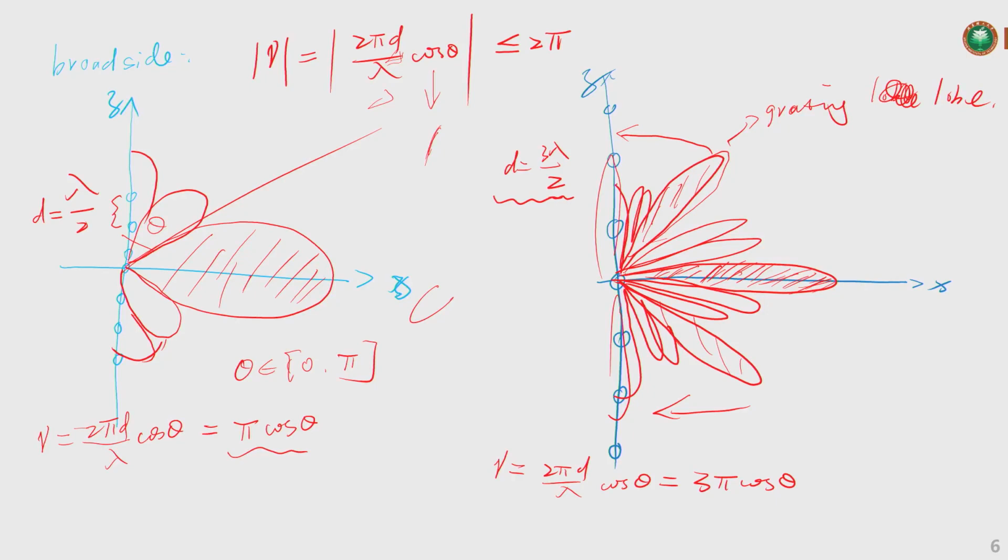And also, we are further considering that if we want to introduce the phase delay between these two adjacent elements and to steer the antenna beam direction, the distance d should be smaller than half of the wavelength, and then we can get efficient control of this part.